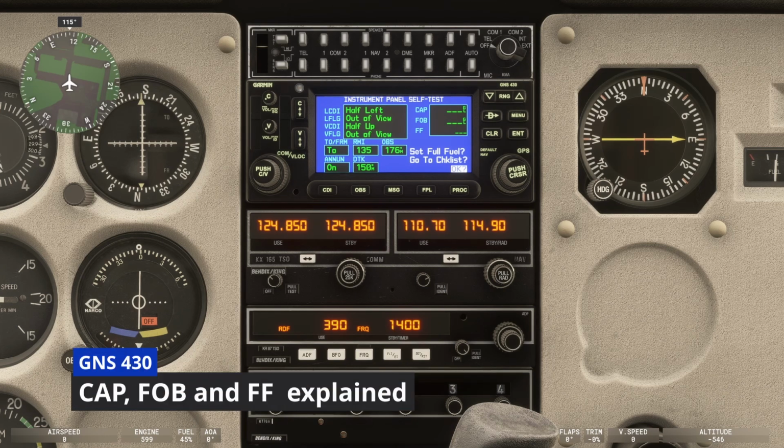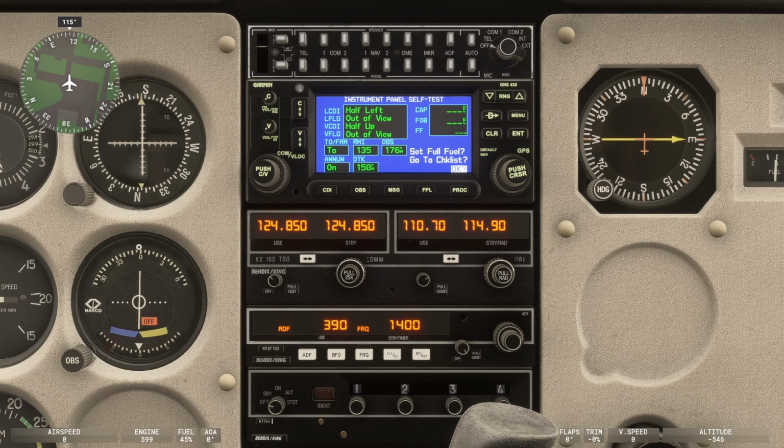Then moving to the top right, where you can see CAP, FOB and FF. CAP means in this case capture, and it typically refers to the autopilot or navigation system capturing a selected course or glide path, right? It indicates that the system has locked onto the desired navigation signal or path. Currently it has been set to nothing. Then we've got the fuel on board, which is the FOB, and this represents the amount of fuel currently available on the aircraft. And it's really important to make sure that you plan this correctly beforehand as part of your flight planning and set it correctly. And then as the last point, we've got the FF, which stands for fuel flow, and it indicates the rate at which fuel is being consumed by the aircraft's engine.